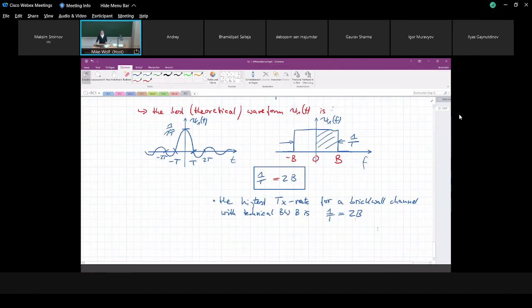And now we have our equation for the channel capacity of such a brick wall channel in bits per second, because now we can say the channel capacity in bits per second is just our symbol rate. What is the rate where we generate these modulated symbols? Times 1/2 times log 2 of 1 plus Es divided by N0/2. This is in bits per second.